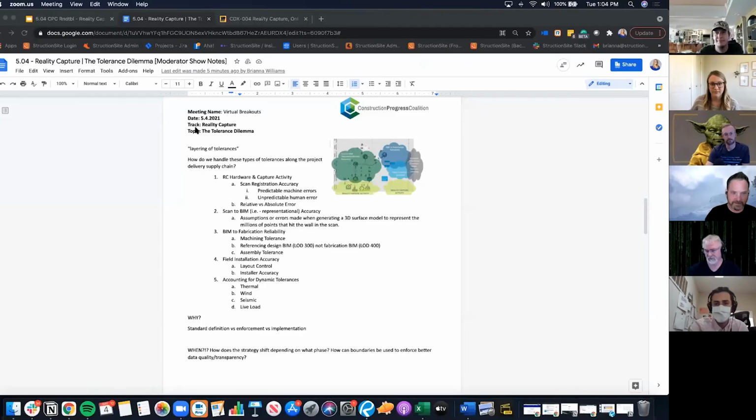I think that goes way back to what Kelly said before. It's having conversations with project teams, like, hey, the BIM model is perfect. And they're like, well, what do you mean by that? And I'm like, well, if it's a 15-foot center to center column grid, that's how it's actually modeled and what we're coordinating to. But if you go out in the field, one column base is 14 foot 11.5, the next one's 15 foot and 3/4. You can't coordinate down to that super accuracy, because then, as David well knows, if you try to prefab to that level of accuracy, stuff's not going to fit.